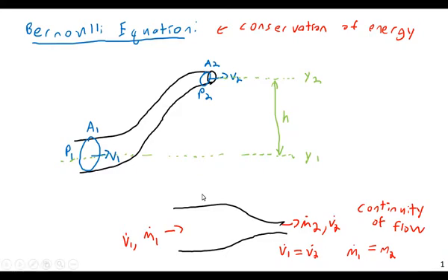So again, if we're looking at something like water, oil, or any type of liquid, we're typically dealing with non-compressible fluids. We're going to be talking a lot about those, and applying those a lot in this class. If we use a non-compressible fluid, in the sense that its volume will not substantially change under different levels of pressure, then the volume coming in will equal the volume coming out.